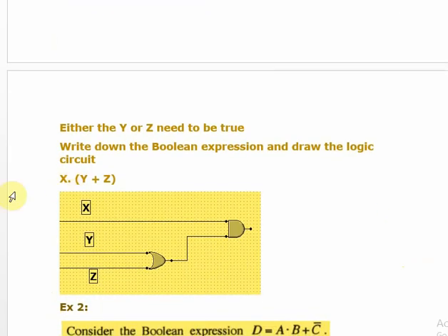Here see, Q is equal to X, one branch should represent X, right? Clear? Directly we are fixing it to the AND gate. The other branch, here we should get Y or Z. Very simple. To get Y or Z, you know, OR means always an OR gate, no? So you put the OR gate and feed Y and Z. So this is the logic circuit.